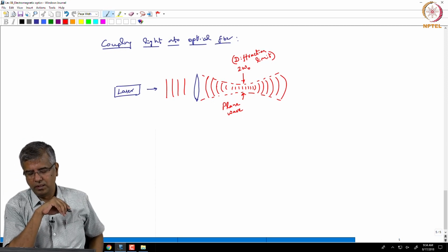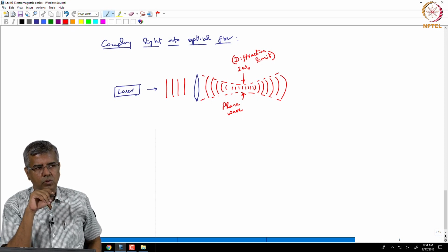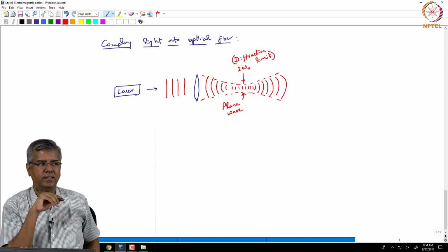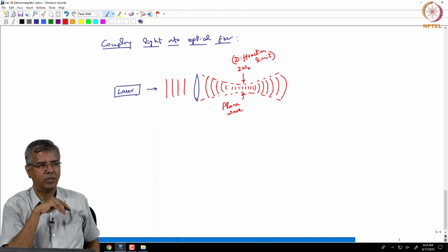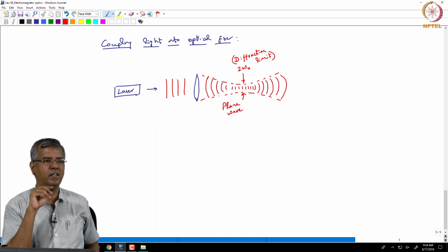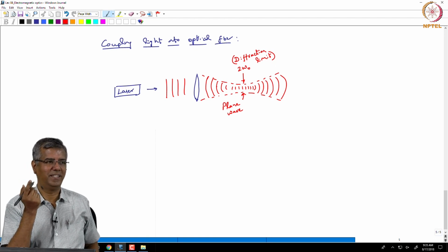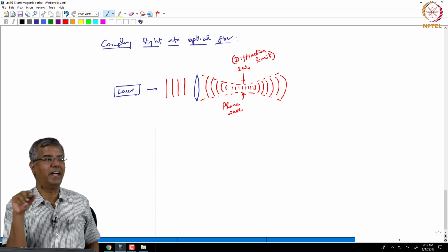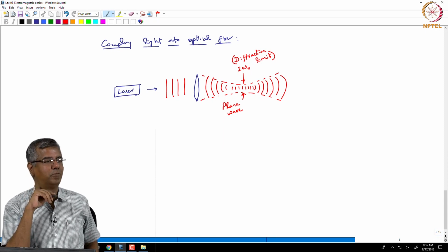Okay, so that's interesting, because when it comes to a single mode fiber, and we saw how the single mode pattern would look, what can you say about the wave vector for the single mode fiber? How many wave vectors does a single mode fiber represent, for the light that is propagating? Well, it is single mode, so it has to be one wave vector, and that is going straight down the center of the waveguide. So what does that constitute in terms of the wave fronts? It's a plane wave front, right.